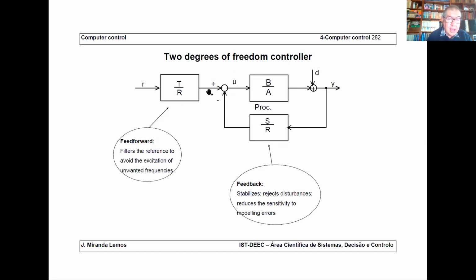Of course, there are some problems related to causality. Later we are going to see. So to do that, you have to put here a polynomial, which is just a forward shift polynomial up to the greatest power of t and s. Okay, but that is something that we are going to clarify later. So bear in mind that if R has an integral action, then you cannot program in Simulink your blocks like this, but you have to move this R to here. Okay.